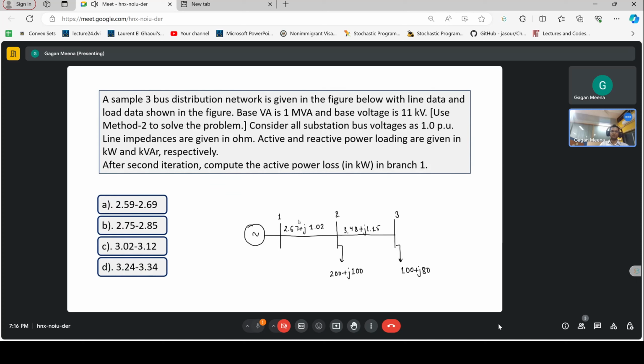So first it is based upon the net load. We make the net impedance model for each branch. So we see at P2 what is the net load connected at bus 2, and it also has to incorporate the losses.